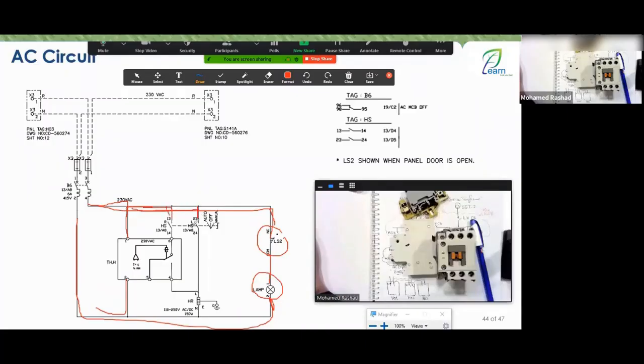So what is the difference between these two? Look, sir, this is a switch for changing modes. Do you want it in one mode or another mode or another mode? Okay, so the mode that is closed is the one in use. The auto mode is the one that is closed. In manual mode, this is the one that is closed. In the off mode, both are open. Okay, so both are open. Now, if I choose manual mode, this will close and that will be open.